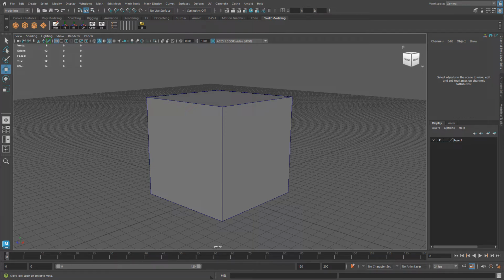Now, as you begin with Maya, the number one mistake that beginners make is working from a default project. So everything in Maya is organized into a project that contains a set of subfolders. And within those subfolders, this is where you keep your files. This is where the images are being rendered to. This is where you place your textures, so Maya can look into that project directory and know where to look for those textures, as well as where to look for scenes that you are saving.